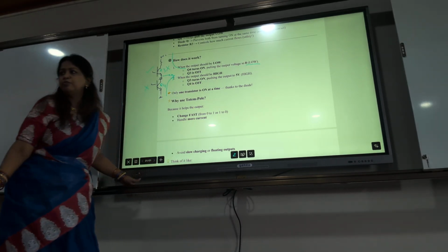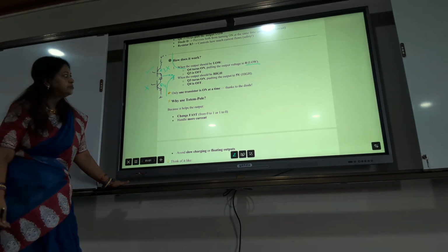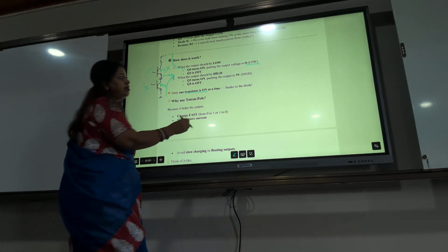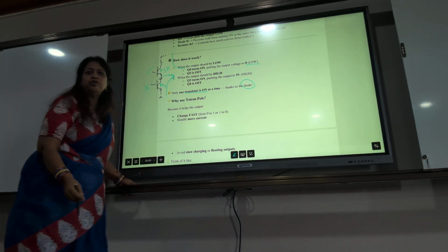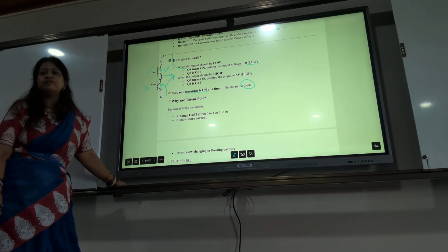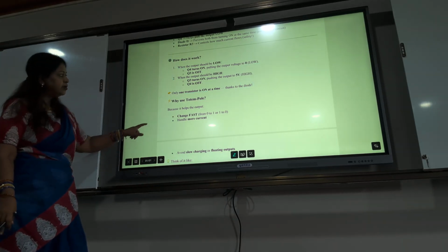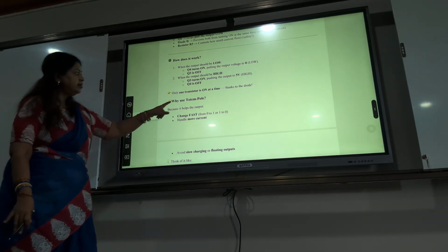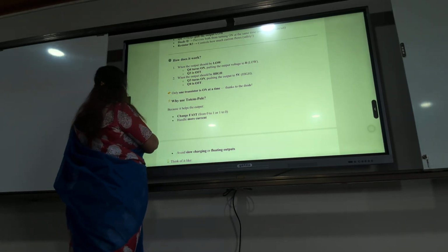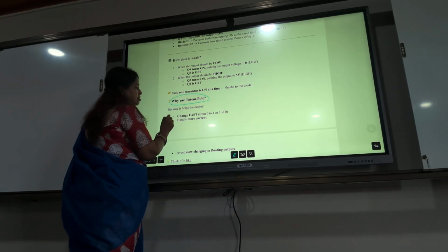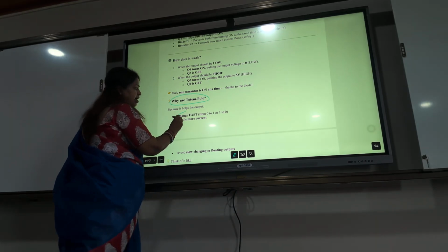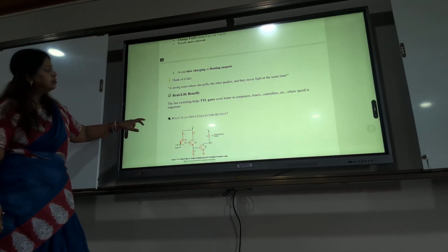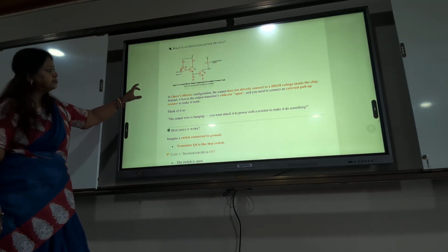When Q3 turns on, Q4 is off. This is connected to VCC. Only one transistor is on at a time because of the diode. The diode is there to make sure that only one transistor is on at a time. Because it helps the output change fast and handle more current, they are using the totem pole. Why we are using the totem pole is because it is faster and also handles more current. So these are the two advantages.